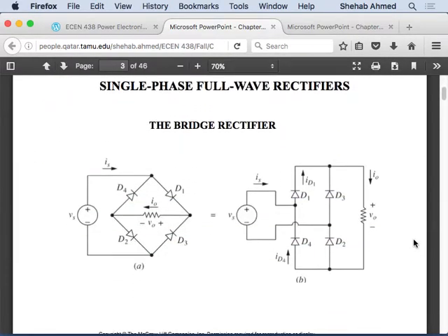You've studied this briefly in 325. I'm sure you've seen some of these circuits. You just didn't go into the deeper analysis of the output voltages, output currents, input currents, etc. So this is what you've probably seen before in 325. This is equivalent to this. We just like to draw it differently in power electronics. Even though this looks more like a Wheatstone bridge that you've studied before, and we actually call it the bridge rectifier, full bridge or bridge rectifier converter, we still like to draw it this way. It's easier to understand and explain when you draw it this way, actually.